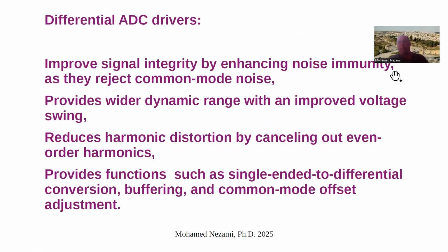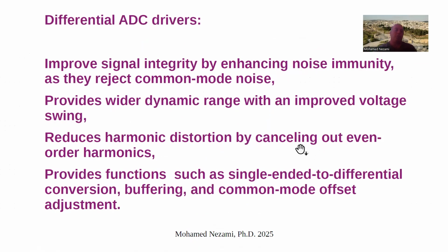So just to remind you of the benefits of differential ADC drivers. Basically, they improve signal integrity by enhancing noise immunity, because of the rejection of common mode noises, so both interferences and noises get canceled. And then it provides a wide dynamic range, or swing, because you're dividing the input voltage into two parts, two separate amplifiers, and then of course it reduces the harmonic distortion.